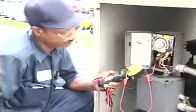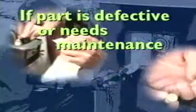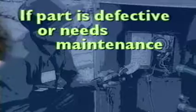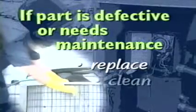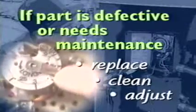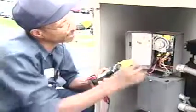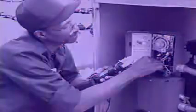When you discover something that isn't working properly, you need to ask why. If a part is defective or needs maintenance, you've found at least one cause of the problem. You will go on to replace, clean, or adjust it. But a good part can perform badly if it's not getting the right input voltage.